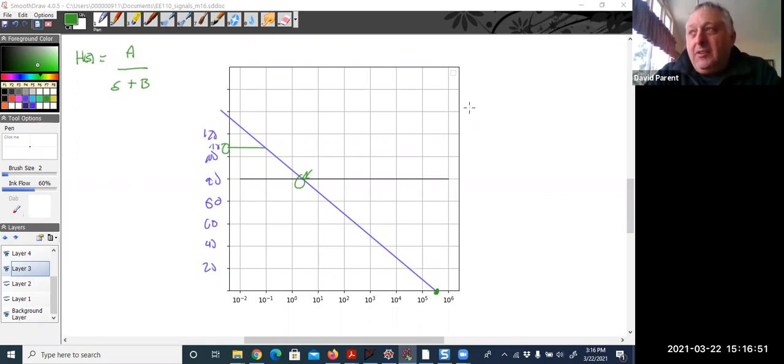I looked in LTspice, it's working there, but it's not working in real life, no matter what I did. It took a lot of debugging, but in the end, I realized that the gain bandwidth wasn't what it said in LTspice. You look up the data sheet, and it was more towards the minimum. So that's why it's kind of important.